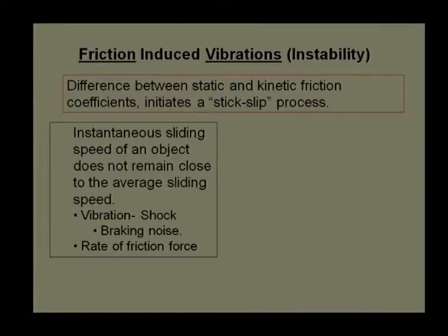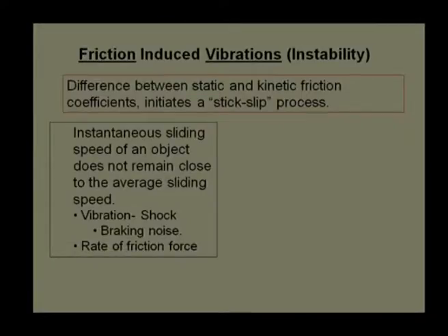These phenomena are often known as shock phenomena, but we are trying to get a feel from that. Sometimes material is in contact and sometimes it is not there. So, there is a continuous jump phenomenon, shock phenomenon, which keeps going on as one surface moves relative to the other surface. And this is very, very common in braking, in the brake shoe and disc, brake shoe and drum. This is a very common phenomenon.